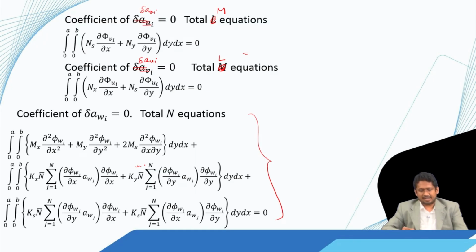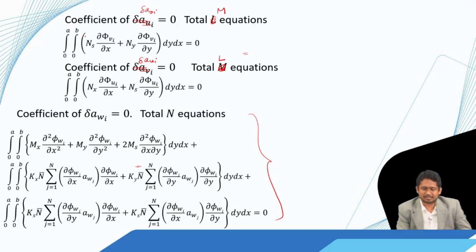Now, if I arrange these equations in a matrix form. Before that, when the B matrix is 0, that means the laminate is symmetric. In that case these two equations are uncoupled from this equation. If I look at the expressions in Mx terms I have B arising, in Nx, Ny I have B arising. So, if B is 0, that means the coupling is not present. We have seen that before also in static analysis.